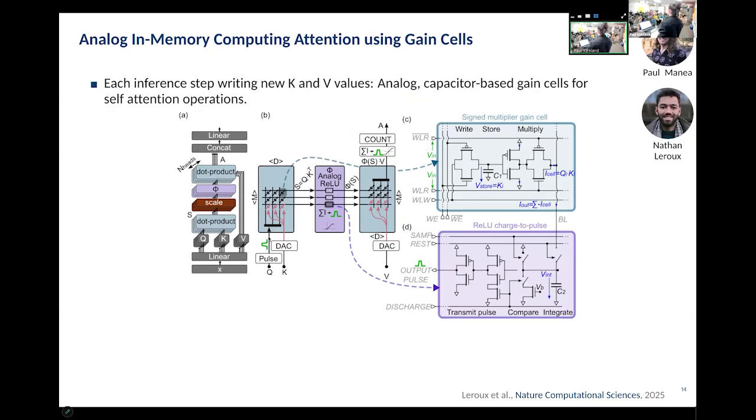But later we had some people come over and talk to us about gain cells, which is basically a charge-based memory, which you can read out using a transistor. You can read out the current on the output transistor, which means that this is something like a DRAM with non-destructive reads. It is just like DRAM; it does leak, right, because of the input transistors that dump the charge onto this gain cell.